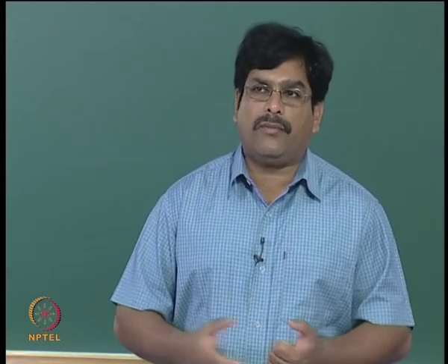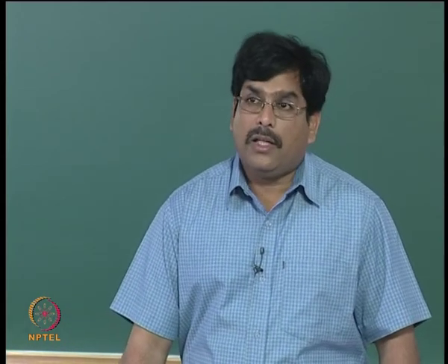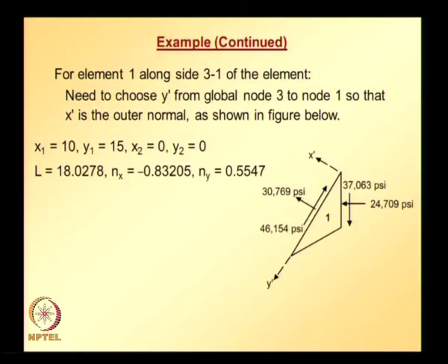Using that information we can easily calculate the normal and shear components along the interface 1 3 or 3 1, and for that we need to know the element length, the line segment length connecting nodes 1 and 3. So for that we require the coordinates of node 3.